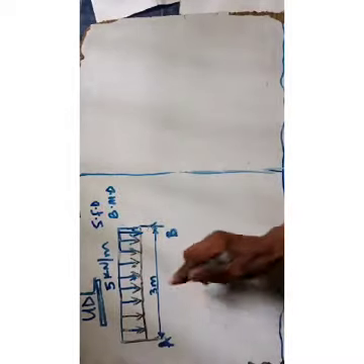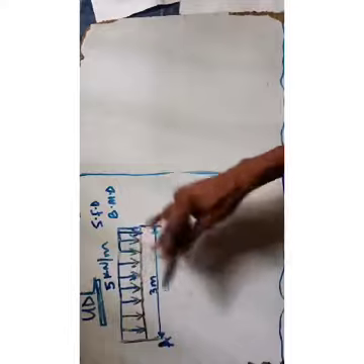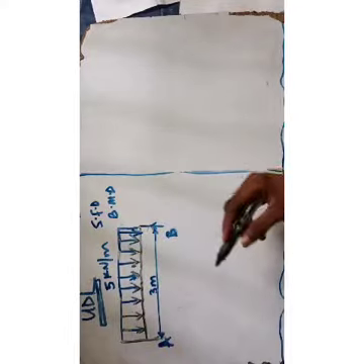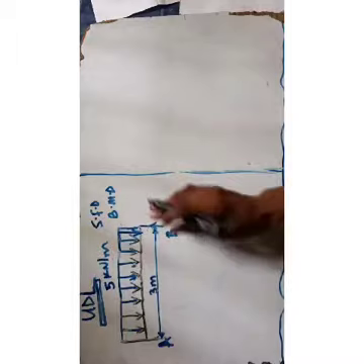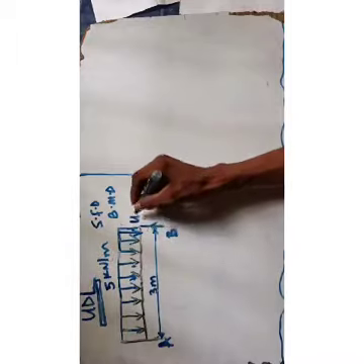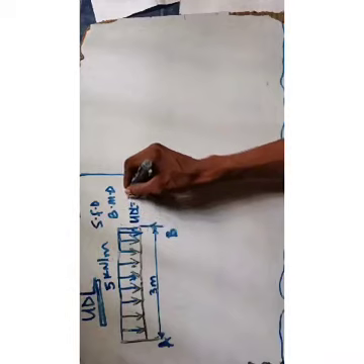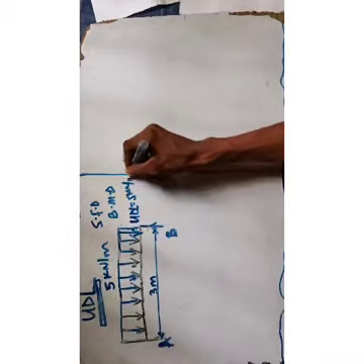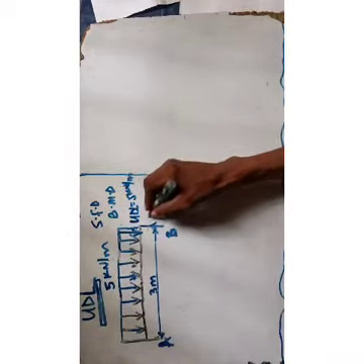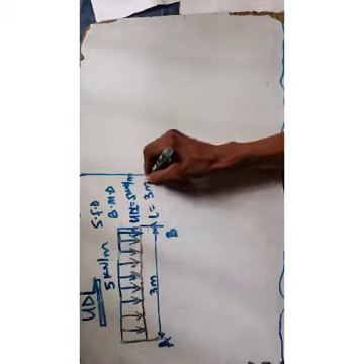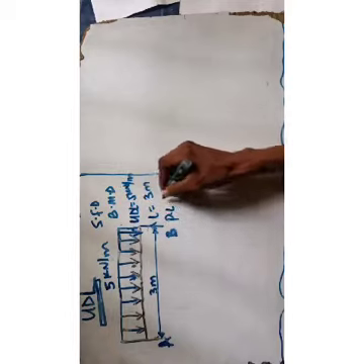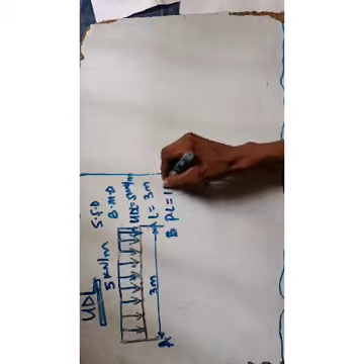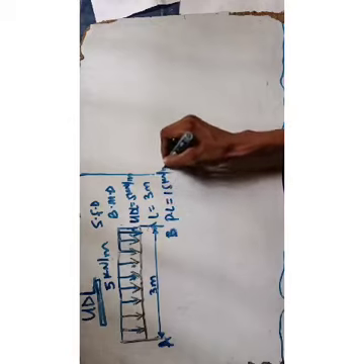This is a UDL question, uniform distributed load. Then the next thing you do is you first of all write the parameters out. So you have the uniform distributed load to be 5 kilonewton per meter. Okay, you have the total length to be 3 meter. Then you have your point load. Your point load will now be what? 5 times 3, and that will be 15 kilonewton.